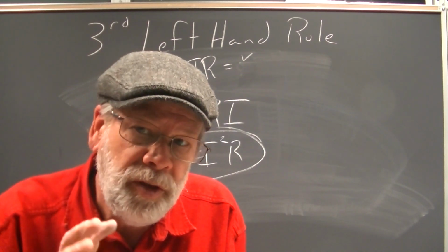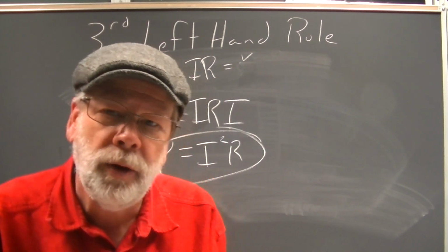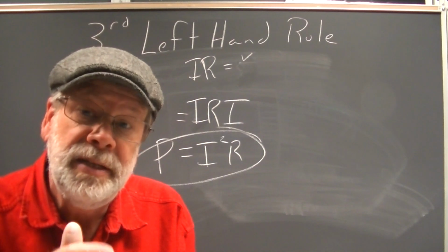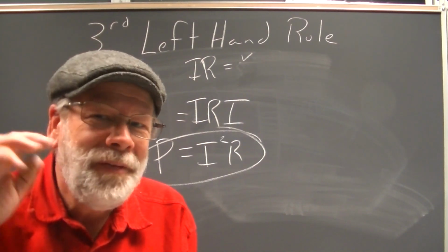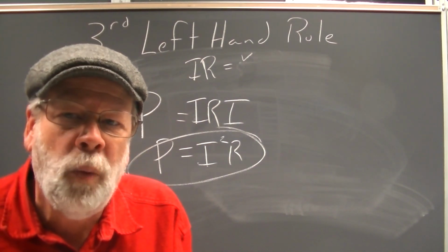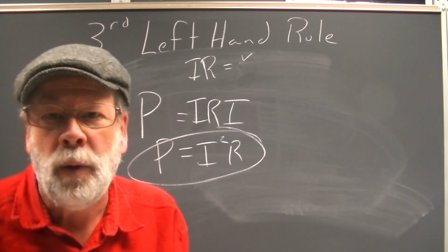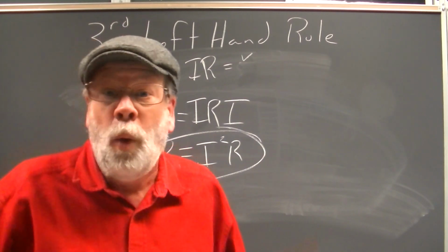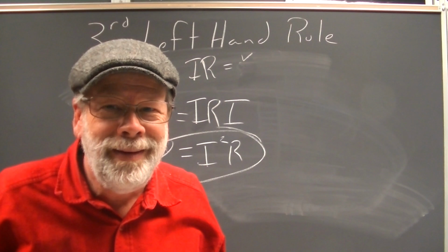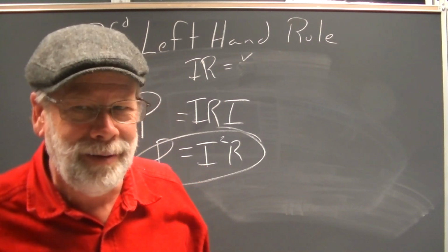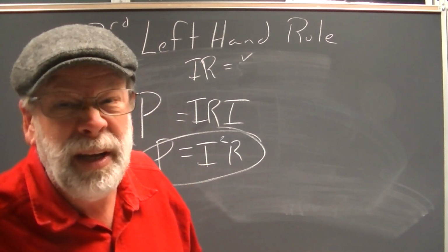Okay, we're talking the power you lose in the wire is the resistance times the square of the current. So if I could decrease the resistance of that wire, that would save some power. So what could I do to do that? Well, I could make the wires out of silver. Why aren't we going to do that? Doesn't take a genius to go that would be a little pricey.